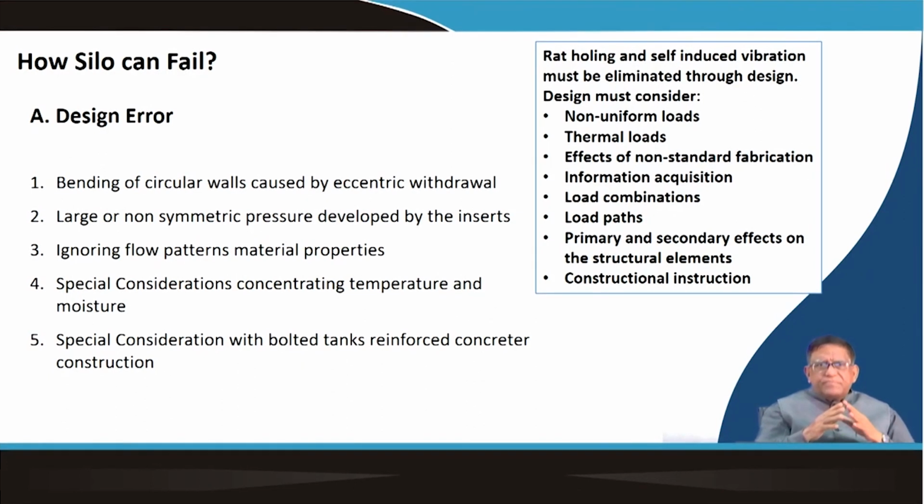Then there is the flow pattern that we discussed earlier, whether it is mass flow or funnel flow. Depending on the flow pattern and the material property, if they are not properly selected, there could be some failure, because if you give different vibrations, at that time you may induce different stress.